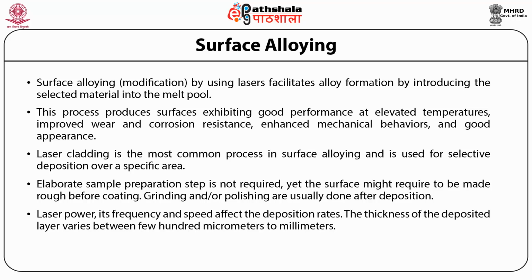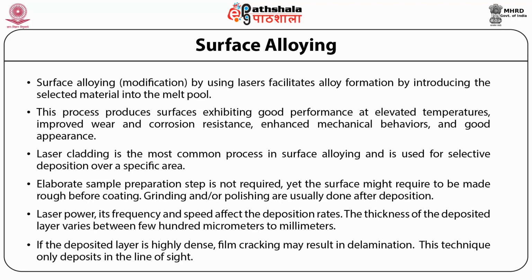Laser power, its frequency and speed affect the deposition rates. The thickness of the deposited layer varies between a few hundred micrometers to millimeters. If the deposited layer is highly dense, film cracking may result in delamination. Furthermore, this technique only deposits in the line of sight.